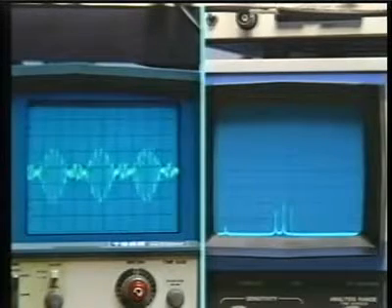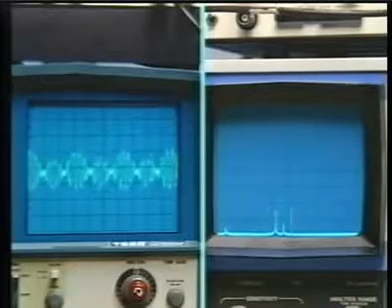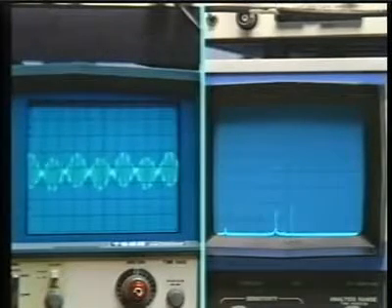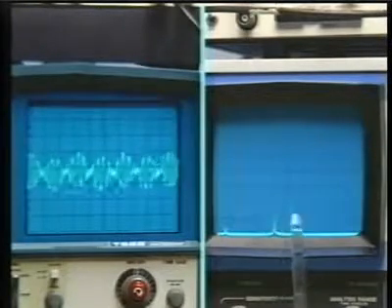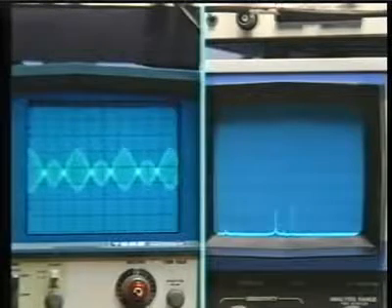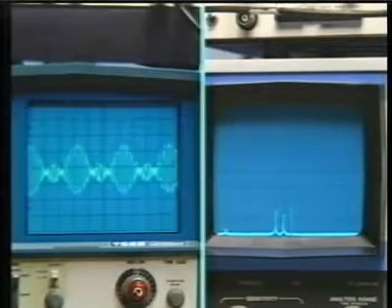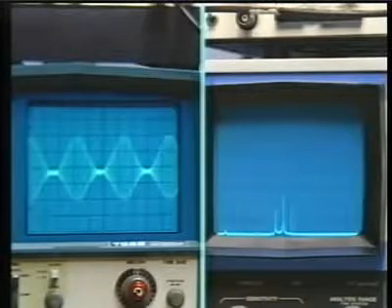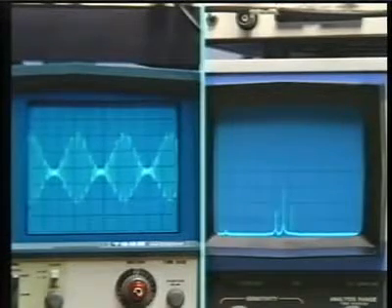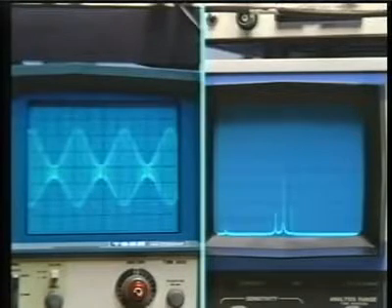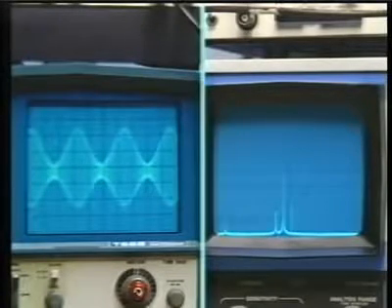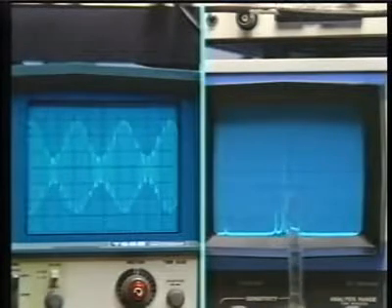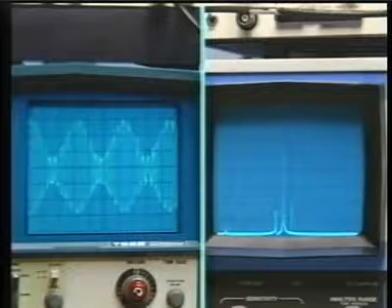And as we decrease the amount of carrier, in fact going down to no carrier at all or almost no carrier, that's suppressed carrier, we have only the two sidebands and the signal is now highly overmodulated. We bring the carrier back up, and when we do that, then we are reducing the percent modulation, and simultaneously, obviously, related to that is changing the carrier level.